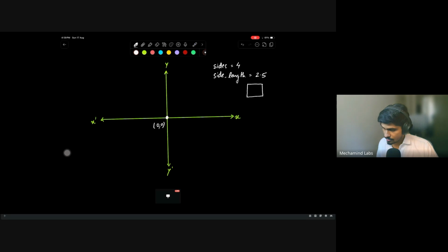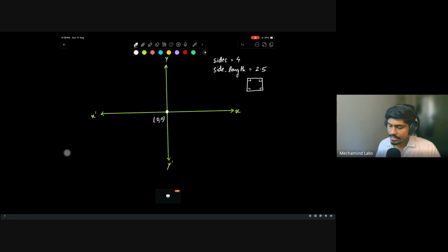So what is the logic we'll be using in the program? I'm just explaining you guys. Since you saw that we are subscribing from the pose topic, what is the pose topic used for? It continuously tells me where the turtle's x y coordinates currently are, like where is the turtle now in the entire turtlesim frame. Initially the turtle will be at center or at rest. So we will initially capture the current position of the turtle, which in our case, let us keep it as 0 comma 0.